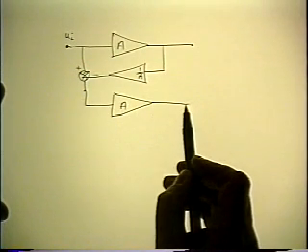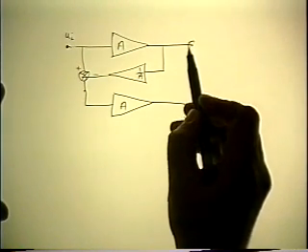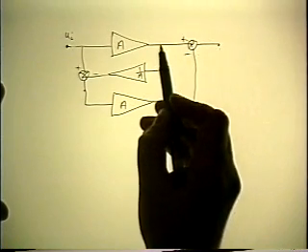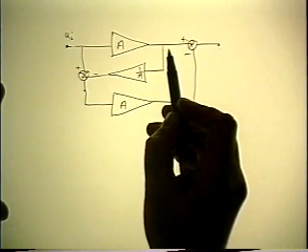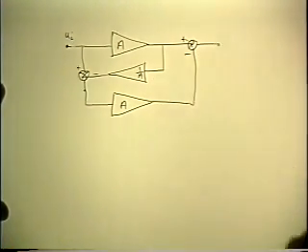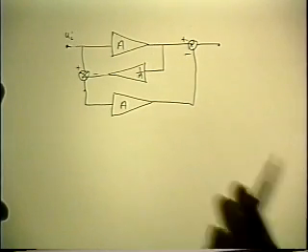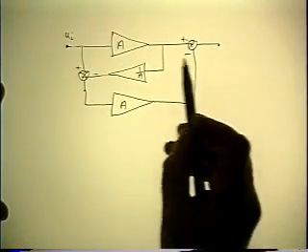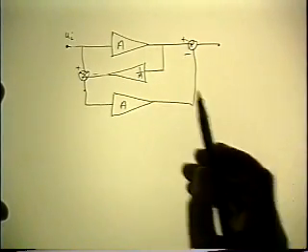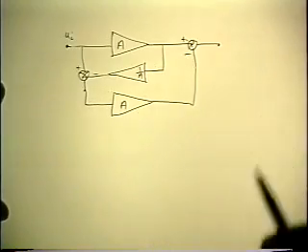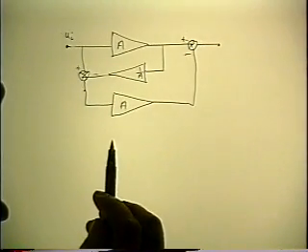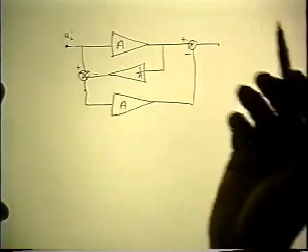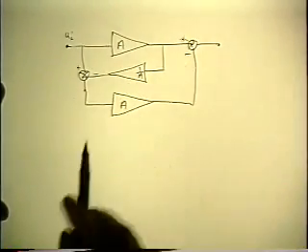So we now have harmonics of the same amplitude that we had to begin with, and we'll subtract those out, leaving the amplified fundamental and no harmonics, which is the objective. So we've now eliminated the distortion of the amplifier. We've now made it act as though it were linear, even though it's really not. So that's getting around the side of the brick wall. The tube's still lousy, but we've overcome its consequence.